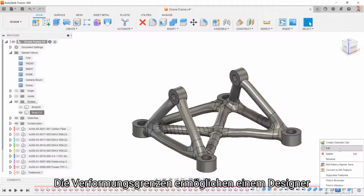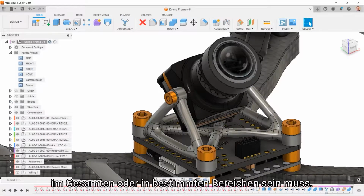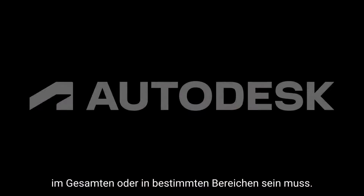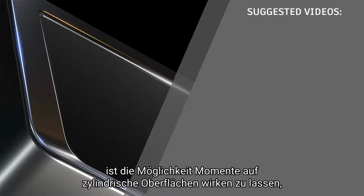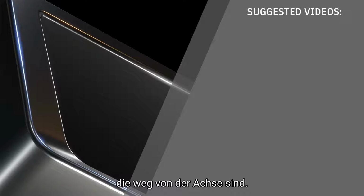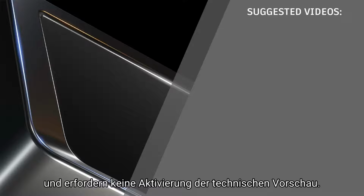The displacement limits now allow for a designer to specify how stiff a design needs to be on either a global scale or in specific areas. Another feature out of this release is the ability to put moments on cylindrical faces that are off-axis. All of these features are part of the core solver and do not require tech preview settings to be enabled.